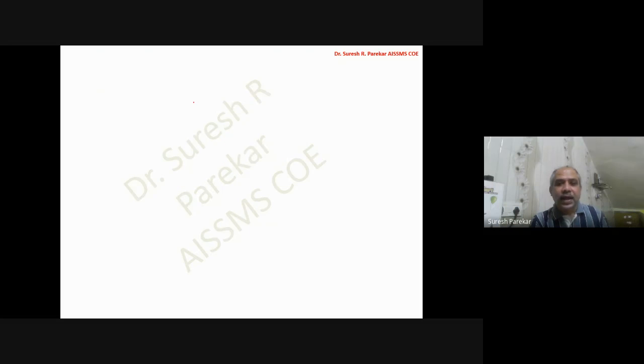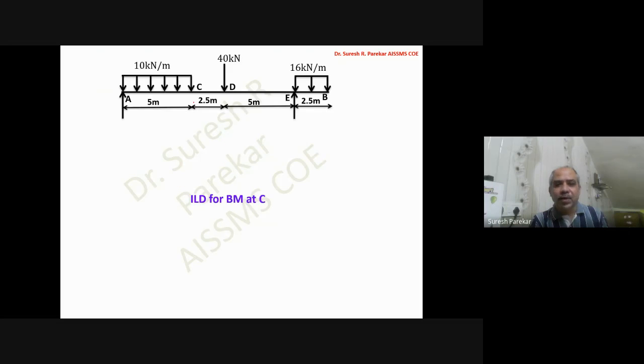That is correct. And now we will go last, that is bending moment. We have to find out at C, which is 5 meters. And here we again have between simple supports, that is A and E, and we are going to get this triangle where we have this value as a into (L minus a) upon L. What is the value of a in this? So a is 5. What is the value of L minus a? That is 7.5. And in this way, we find this value: 5 into 7.5 upon 12.5, that is equal to 3.